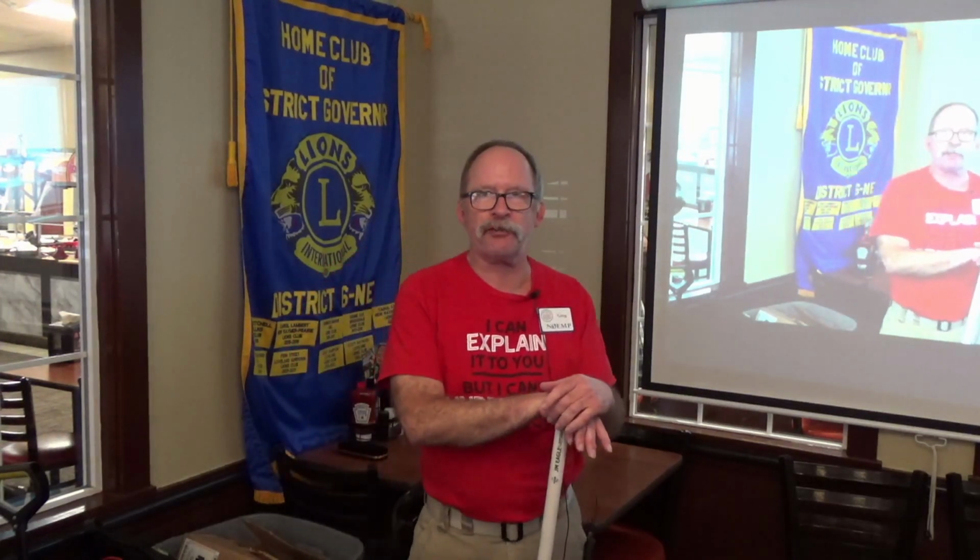So the question was, do I have the chart for random wire lengths? Marty is correct. The term random wire is not actually random. There are good lengths and bad lengths. The idea being, and again I had mentioned this, that you want to stay away from half wavelengths and multiples of half wavelengths.